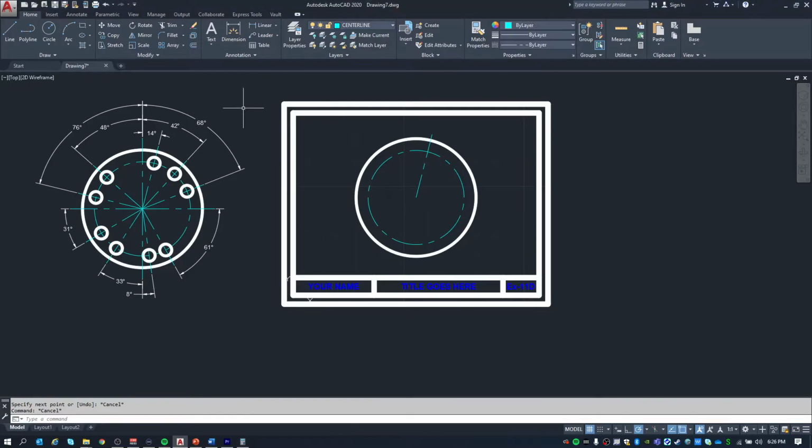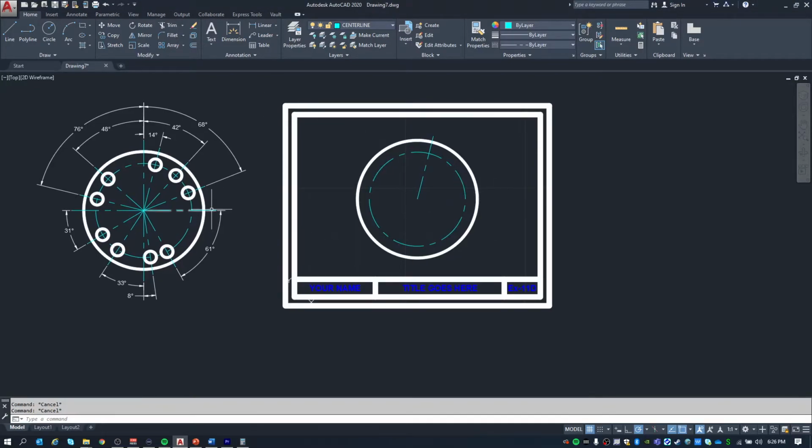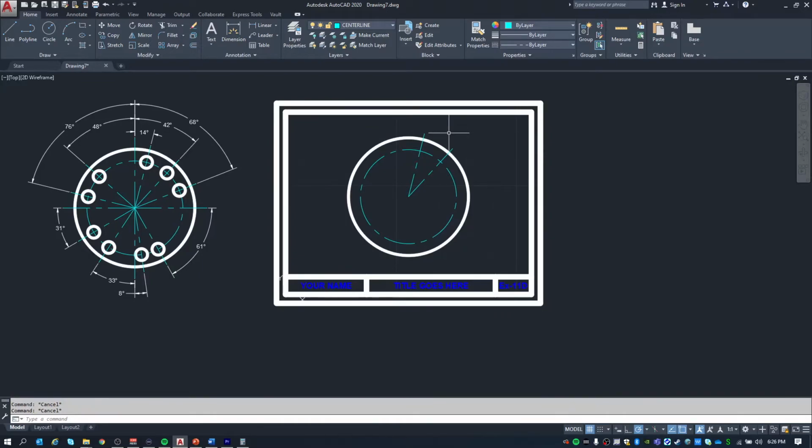So we know that that's going to be 48 degrees from the x-axis. So again, we'll draw a line less than 48 degrees, the 2.75 length. And then there's that one. Okay, so for the next one, it shows that it's 68 degrees from the 90-degree line. So we know when we subtract 68 from 90, we get 22 degrees. So we will do another line that's less than 22 degrees, at 2.75 long. And we have this angle.